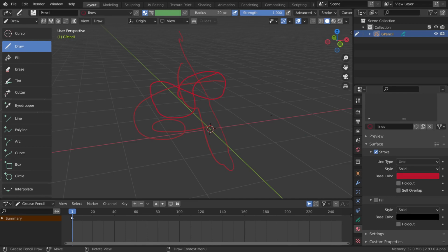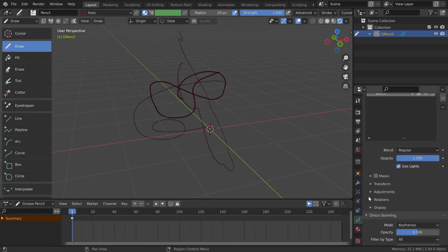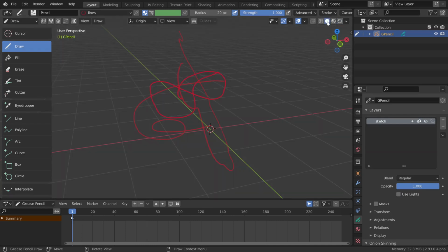The next thing I'd like to draw attention to is this view, the solid shading view, which we can also get this little menu for with the Z key. If we switch to the rendered view, which is the furthest one along, we can see we've suddenly lost that red. That's because if we come over to our layers, by default, every layer created will be set to use lights. So if we just uncheck that, we'll get a much more similar view between our solid and rendered modes.